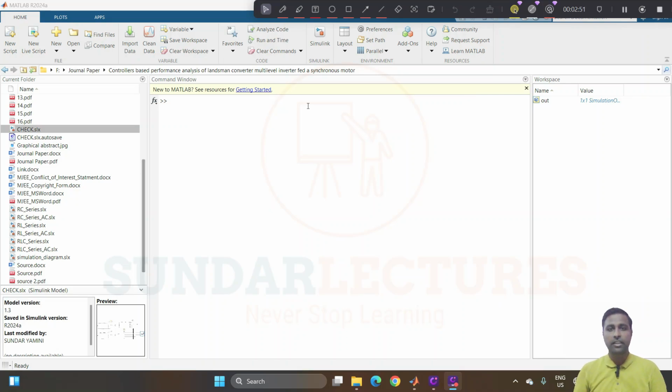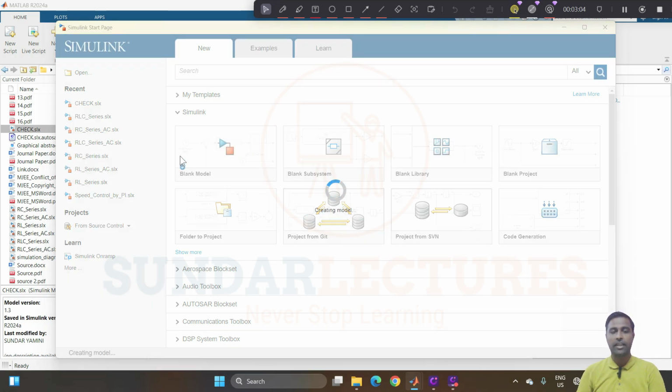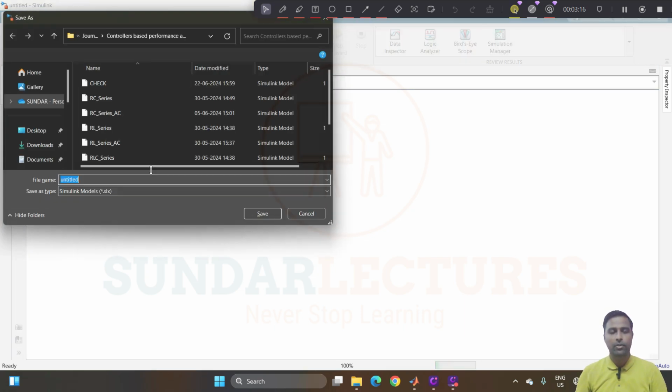We have come to Matlab. I will explain from the beginning. Open Matlab and go to Simulink, then choose create model, blank model. Create a blank model here, and save it in any place, because even if you close it there will be no issues.